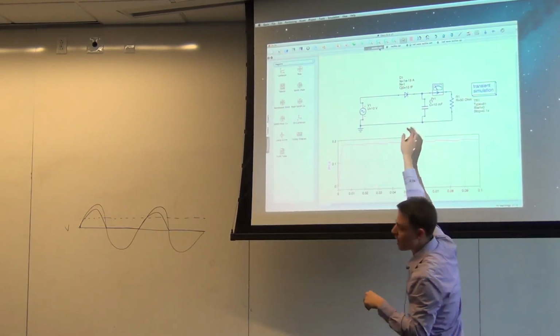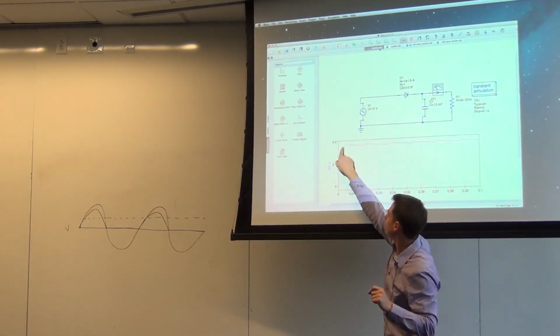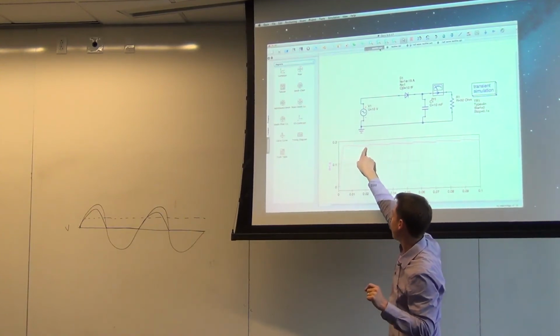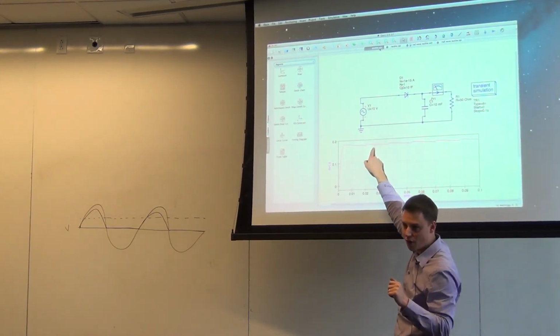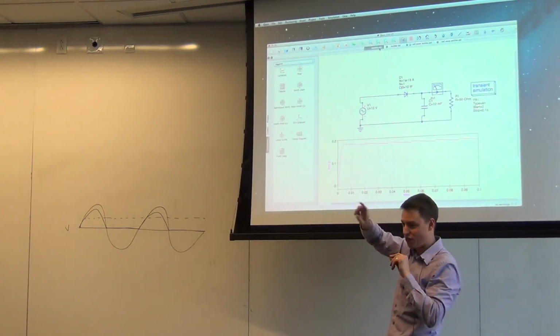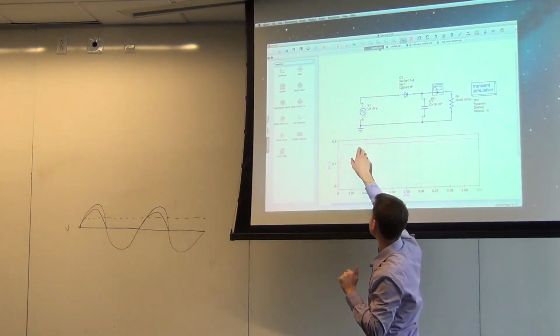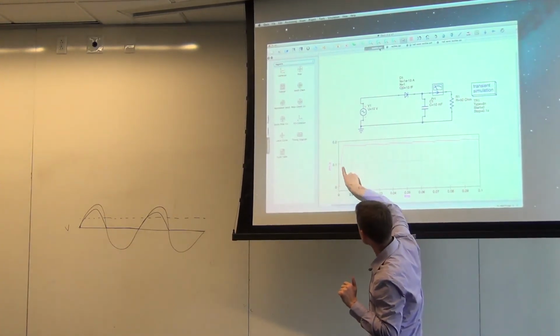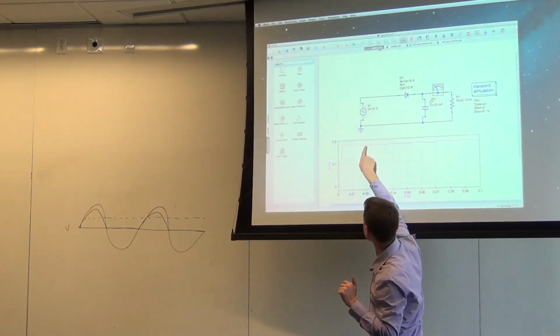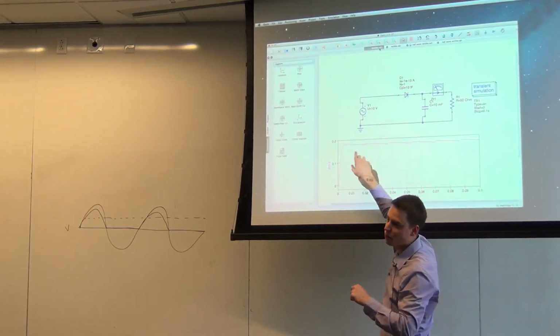But because we add that capacitor there, essentially it builds up charge. Charge drops this whole time. So this whole time is dropping voltage because the capacitor itself is acting as a voltage source. And then when you come to this little lip here again, it will charge it back up, and that will repeat that process.